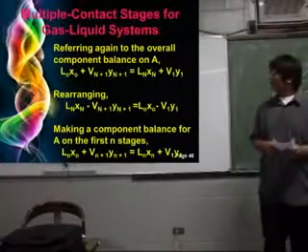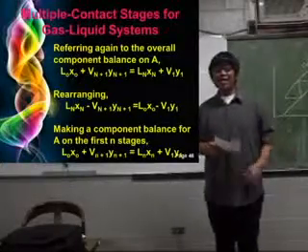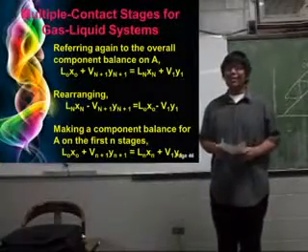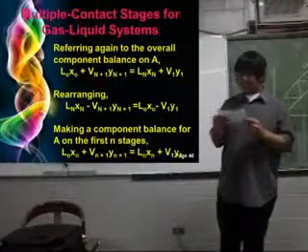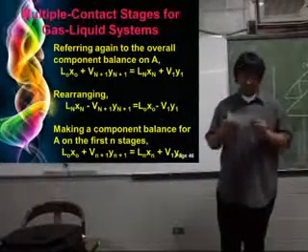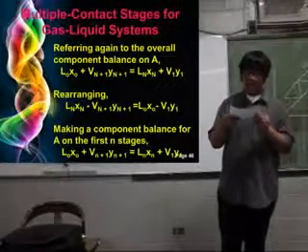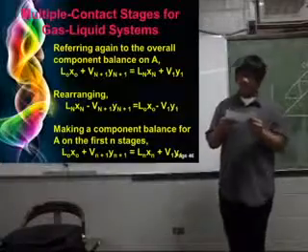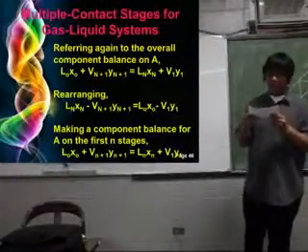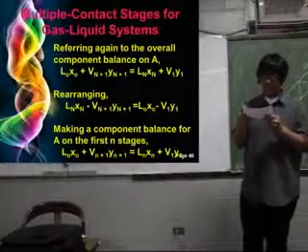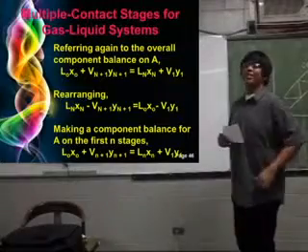Here, we will assume that vapor and liquid flow rates are constant. With that assumption, the operating line equation will become straight. Also, the equilibrium line is a straight line over the concentration range. Simplified analytical expressions can be derived for the number of equilibrium stages in a countercurrent stage process. So let's start the derivation.